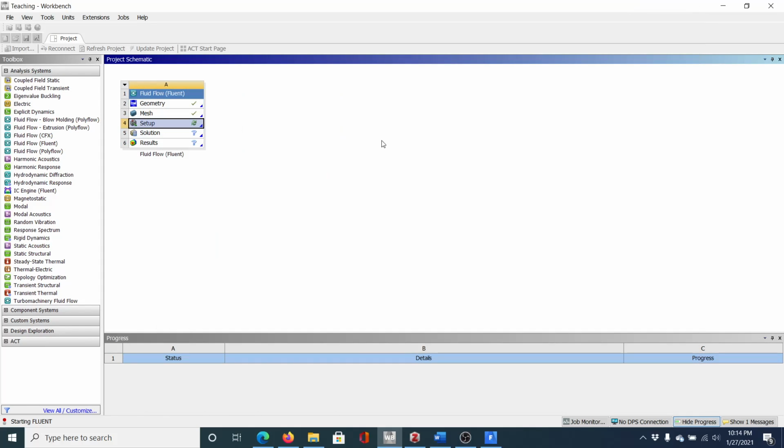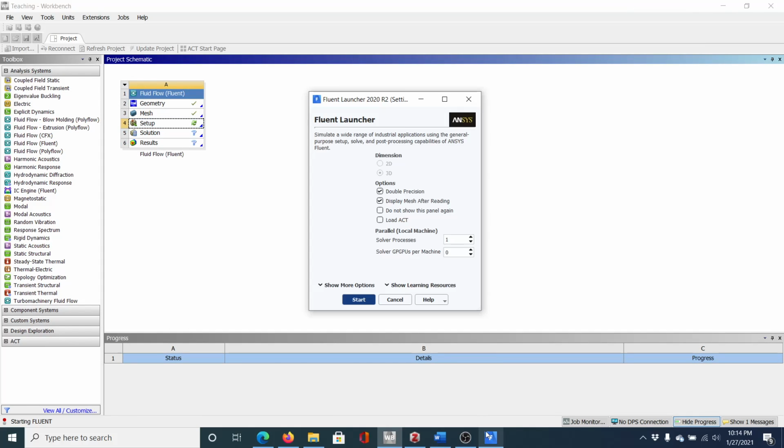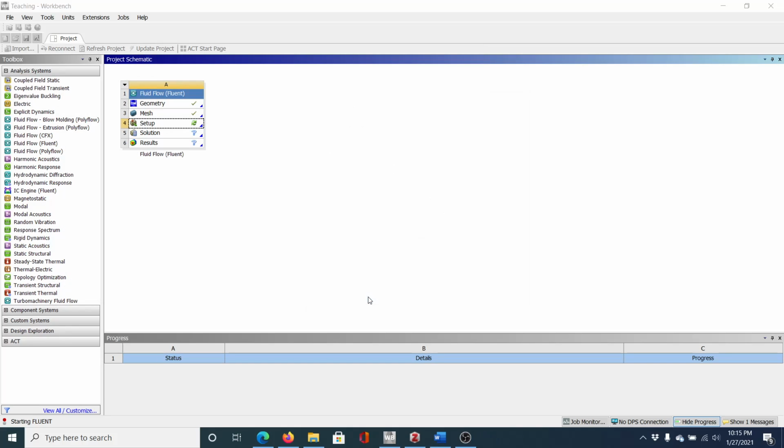So essentially, what this is asking is how many cores do you want to utilize to solve the process? My last computer I had 4 cores, so I would usually just select 2. I wouldn't want to max out the cores. But since I have 6 on this laptop, I'm going to up it to 4 and see. Hopefully, it'll run quicker. When we utilize FIU's computers, obviously we can use 16, so it'll be even faster. And we're going to click Start.